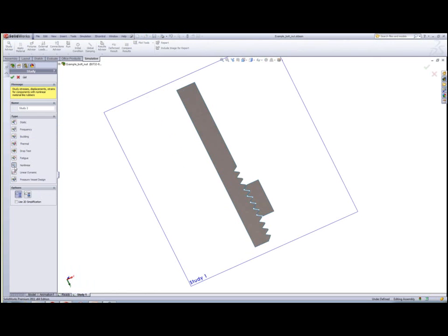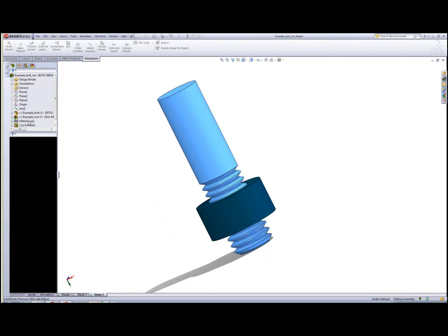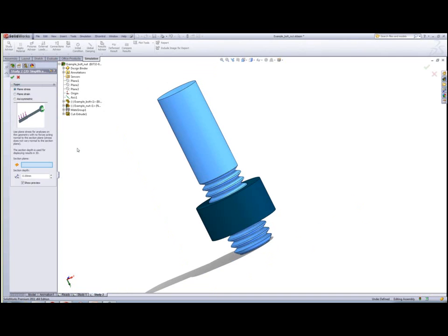Let's say I want to do a nonlinear study. Let's say for this particular model, we're going to do 2D simplification. When I click OK there, you'll see a new little interface. So this is my portion of a bolt and a nut. Now we've taken the thread and we've simplified the thread. This is going to be our assumption. We're going to be figuring out the stress and strain as a result of this nut acting on the thread. So for this, we're going to go in and just simplify our thread and not make it a helical path. It'll make our study a little bit quicker to resolve.